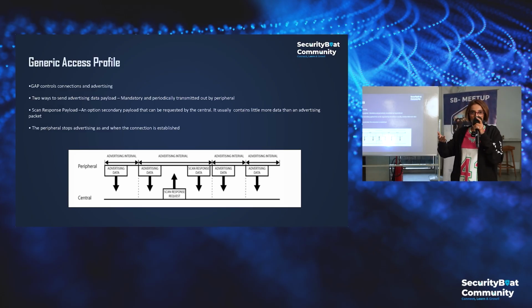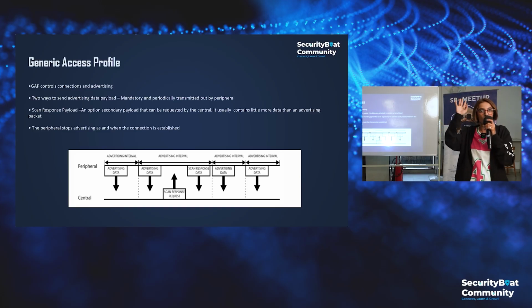Again, it differs from device to device. It is not necessary that every device should have it, but sometimes this response payload can give you some extra information also. And then once the connection is established, the advertisement packet stops. Then it is not going to keep telling, hey, this is me.